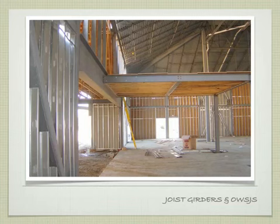So this is a good example. It's hard to see, so I'm going to stand up here and actually point at it, right? So we have to look up really high. The open web steel joists come up these sloping pieces here, right? When we get to this end, there's a column. This, right, is that joist girder truss. Does that make sense? Much deeper, much heavier, right?